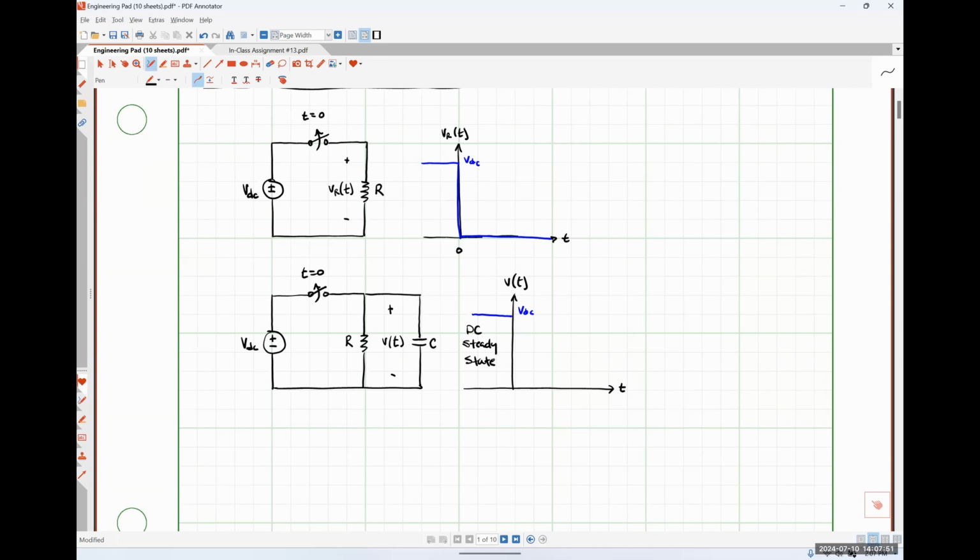Okay, so this is kind of the new stuff here. Does anybody have any thoughts on what might happen? The voltage drop is going to gradually decrease. First, it'll be the same because the capacitor is charged up. Excellent job. I was expecting somebody to say that the voltage would fall to 0, and it will over time, but you're 100% right that it's going to gradually decrease to 0.